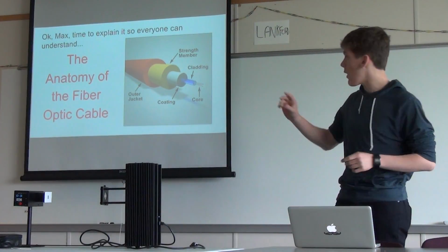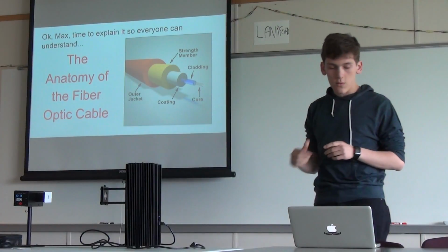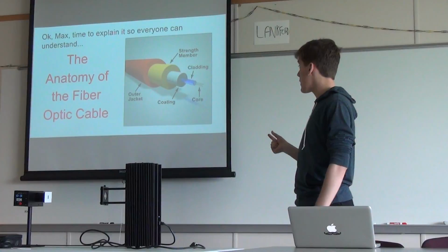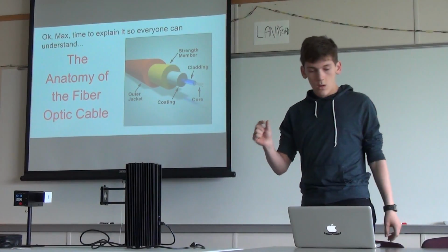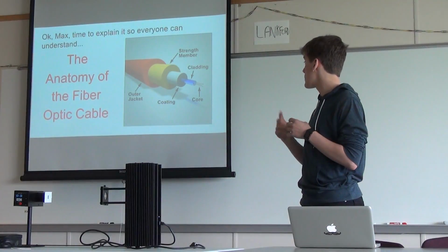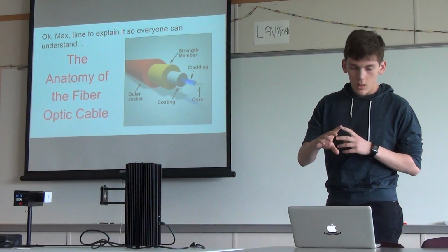There's two types of that single core fiber. There's single mode and multi-mode. In layman's terms, the single mode are smaller and they can transmit data through a laser, whereas multi-mode are larger and can transmit data, light coming from an LED.